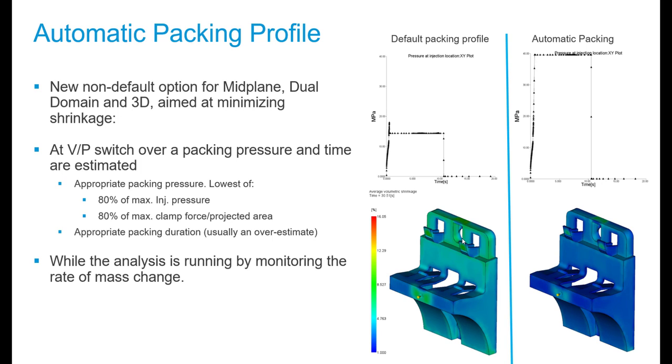So during the packing profile, we're continuing to monitor how much flow rate there is still in the part, and if there's almost no flow rate happening anymore, then we've reached the end of packing, and we can stop it and switch to the cooling time.